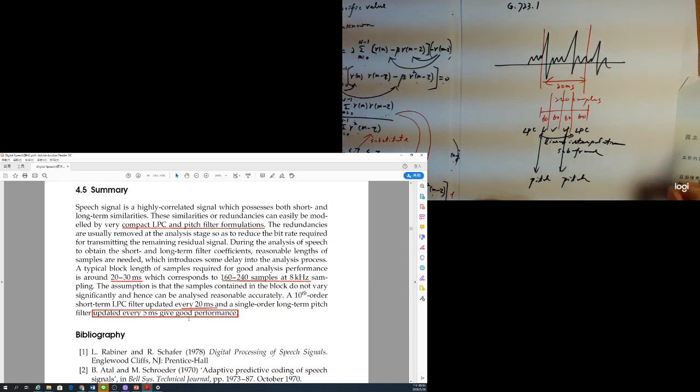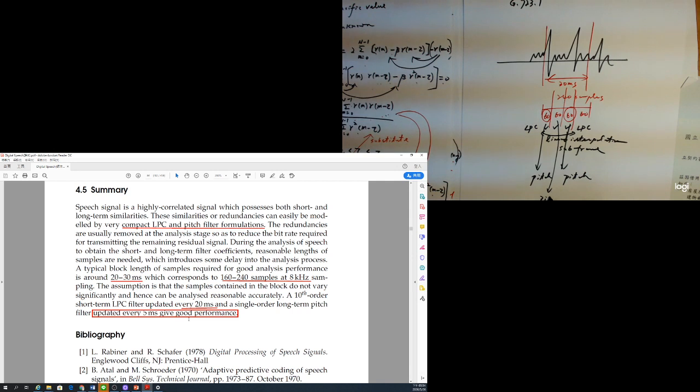So your LPC has a little bit of variation, and also they have a pitch here. The pitch search uses the subframe. So you have pitch 1, pitch 2, pitch 3, and this one will be pitch 4. Pitch 1 and pitch 3 will be searched, and pitch 2 will be according to pitch 1 with some variation. The variation will be +1, +2, 0, and -1.